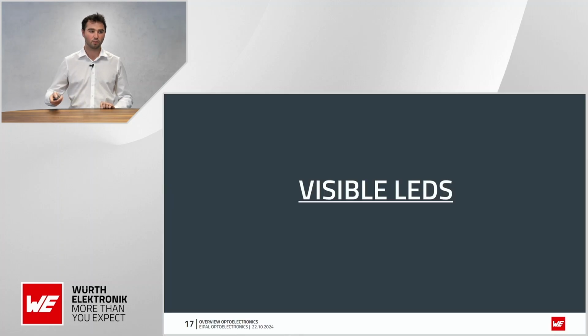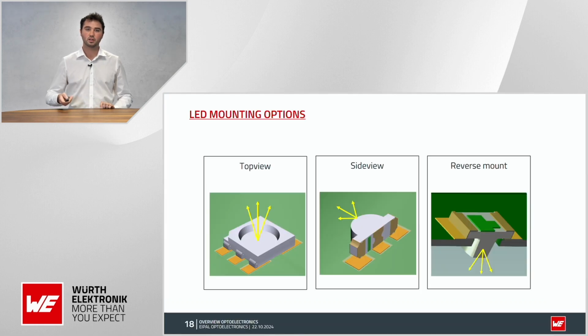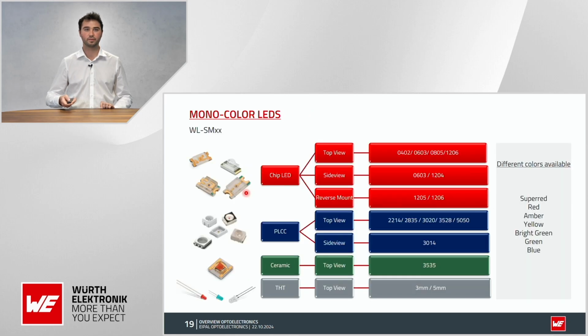Okay, now I want to give a quick overview of different products in our portfolio. First, visible LEDs. We have them in all different possible mounting options. Top view, they emit light to the top. Side view, they're soldered sideways and emit to the side. Reverse mount, they emit to below if you have a hole inside of the PCB.